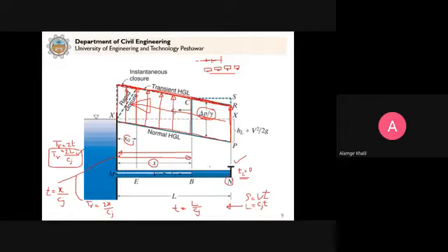So it means that in this round trip, the wave starts from here and then comes back here. But as we move upstream, this time is reducing, because the time the wave takes to go from here and come back is less than it is for the valve. If you consider any point here, the wave takes this much time to come back. This is TR for this distance, let's say x naught.